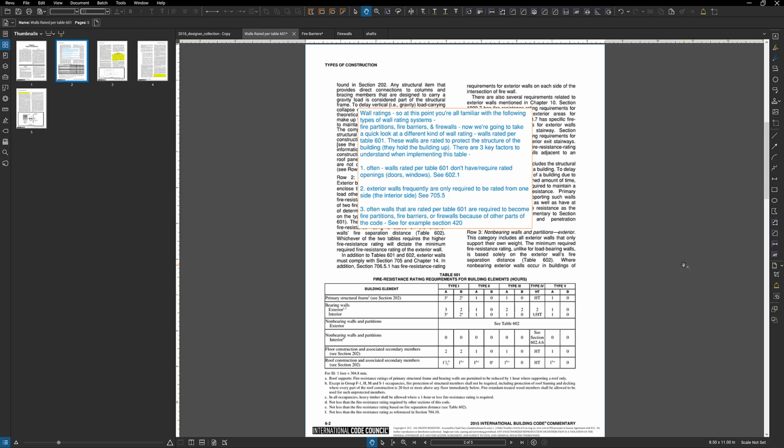So in general, an architect would need to prove or somehow substantiate that these walls are going to perform at 1 hour or 2 hours or 3 hours or 4 hours, or whatever it is we say that they are going to perform. So how do we do that, right? Well, you can do performance-based within the International Building Code. For example, if I do an 8-inch thick concrete wall, and the concrete is of certain strength and has certain properties, then I can deduce or reference by the building code that that wall is going to have a 2-hour fire rating.